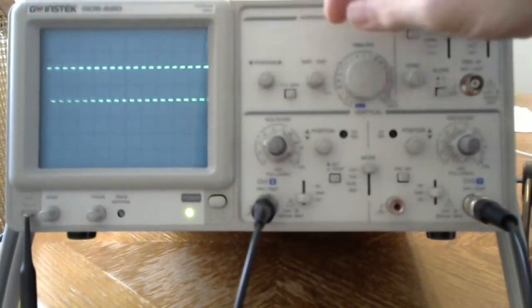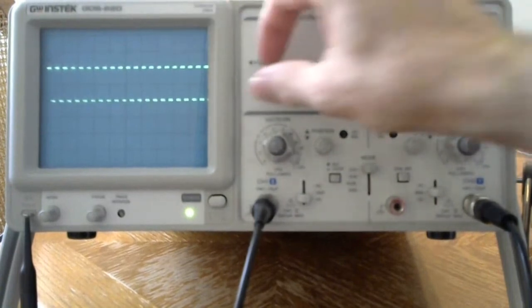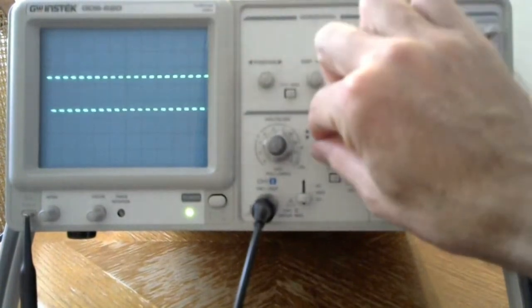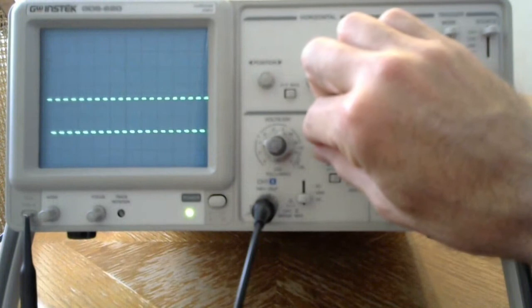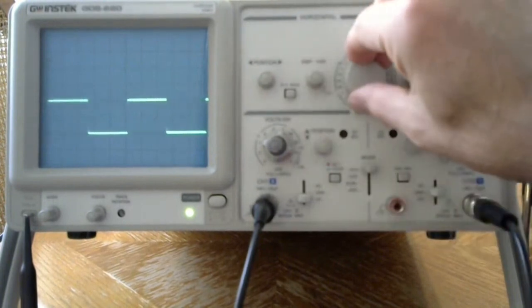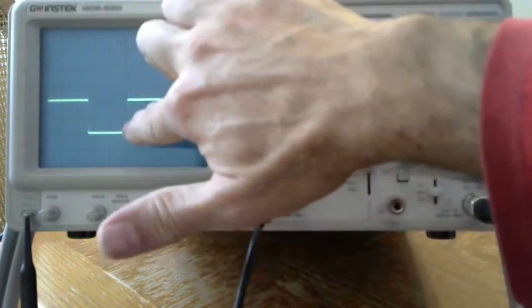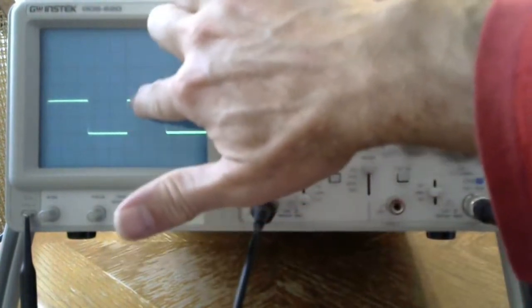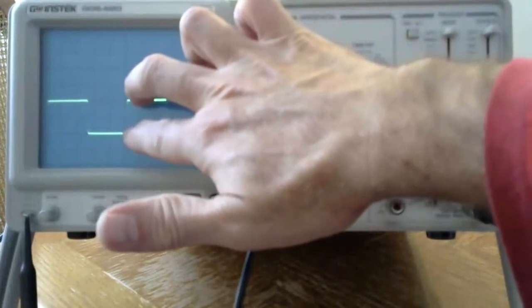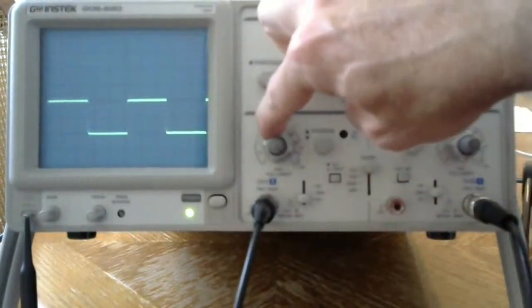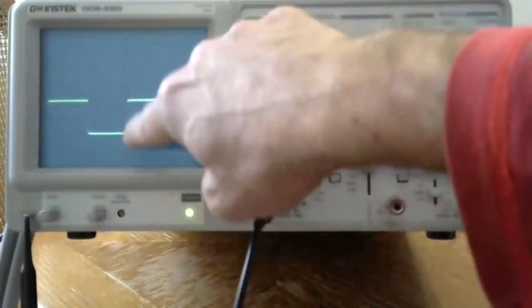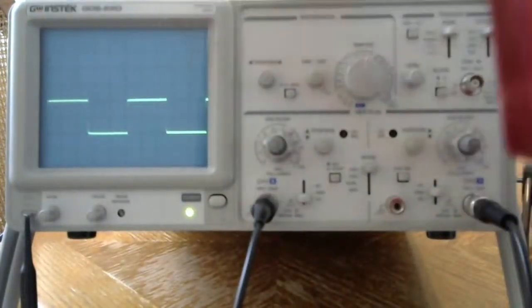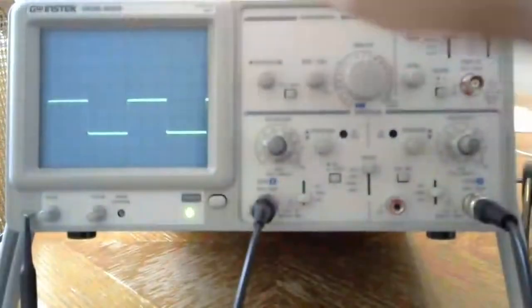It's hard to measure that because my scale is so big. So in order to actually measure it, I'm going to move my signal to a convenient place, like there. And I'm going to change my time base. And notice how I have between this point and this point 2 boxes. That's 2 boxes from here to here. And my scale is 1 volt per box. So this vertical distance is 2 volts. Well, my calibration says 2 volts peak to peak, 2 volts. That matches.